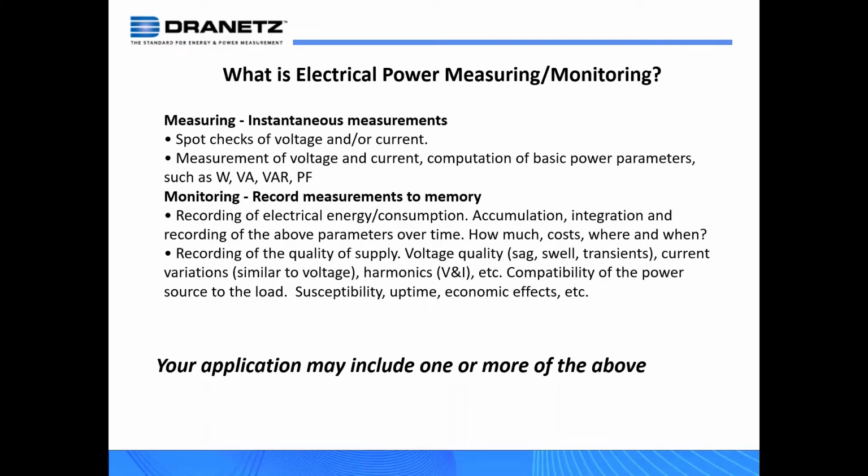And so usually any time one wants to spot check, say, I suspect I may have a low voltage reading at this particular outlet, you're usually going to deploy something like a digital voltmeter to spot check. Monitoring could relate to that same scenario where I'm suspecting I'm getting low voltage at, let's say, an outlet. So I want to monitor over a period of time to see what that profile is.